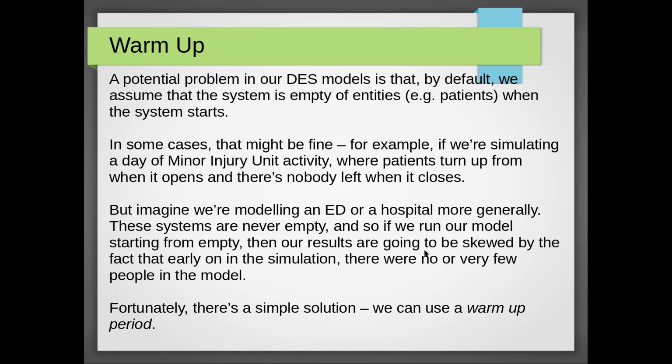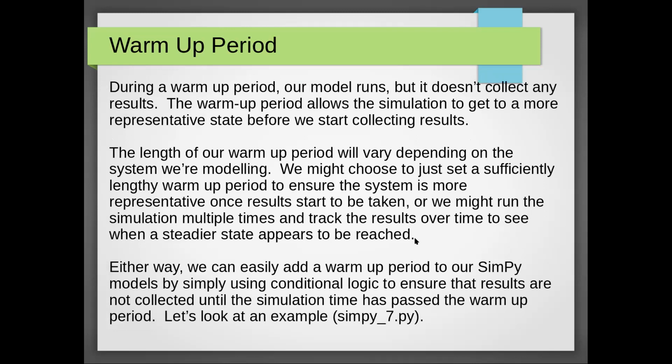So what we want is a solution that allows us to somehow capture the fact that the system that we're modeling is not going to start off as empty, assuming that's how your system works. To do this, we can use something called a warm-up period. Basically, what a warm-up period does is it runs the model as normal, but during the warm-up period, it doesn't collect any results.